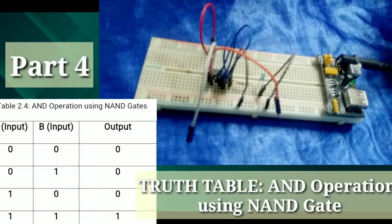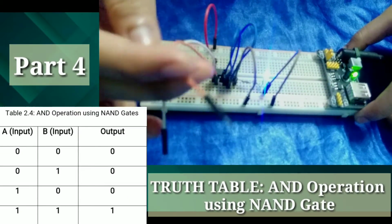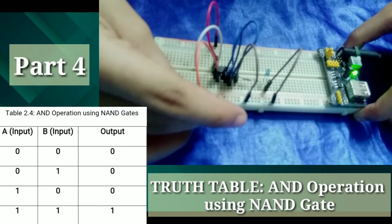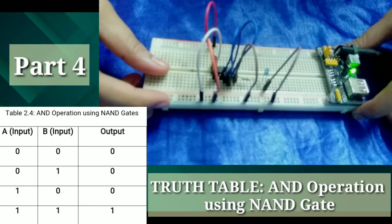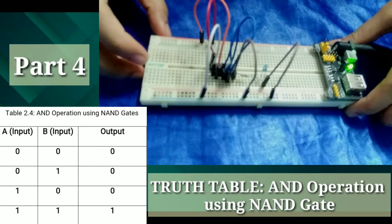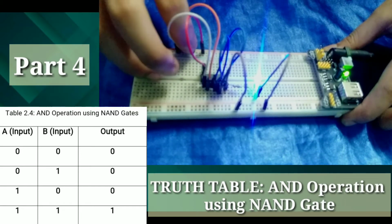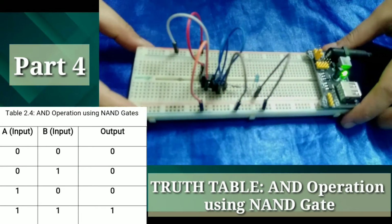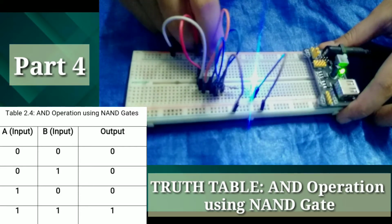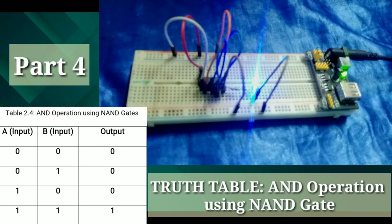Now for part 4's truth table, remember, white is for A, orange is for B. If both of the inputs are at 0, you can see the LED is off. If A is 0 and B is 1, again, the LED is off. If it is interchanged, A is 1 and B is 0, again, the LED is off. And if both of the inputs are 1, the LED is turned on. That's the truth table for part 4.